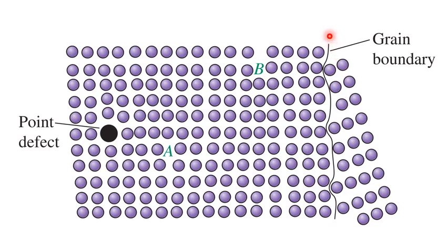and this leads to an increase in the strength of the material. Thus, we can increase the strength of a metallic material by increasing the grain boundaries, or in other words, by decreasing the grain size.